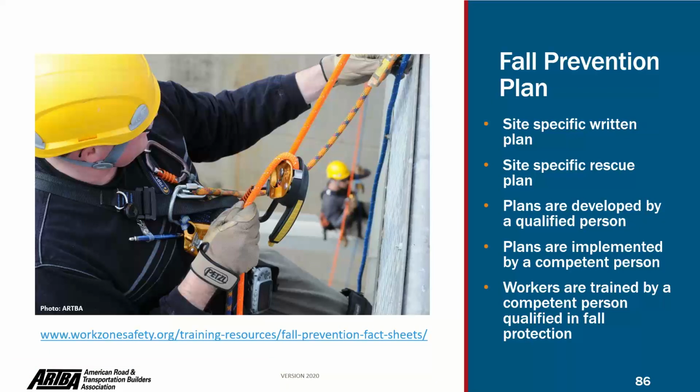So for a fall prevention plan, again, it should be site-specific. It is not a generic product. It should be customized according to the circumstances in which we are going to work, identifying specifically each hazard according to the work zone in which we are working. There should be a site-specific rescue plan, because you need to identify where the firefighters, the policemen, and the rescue personnel are, and you have to train your workers that are working in this specific area.